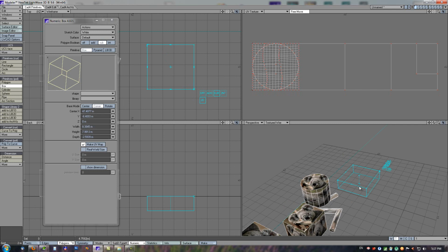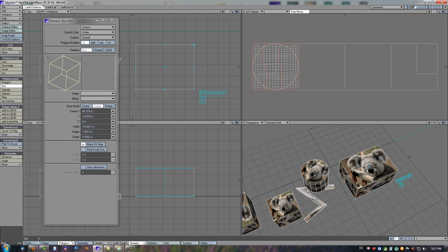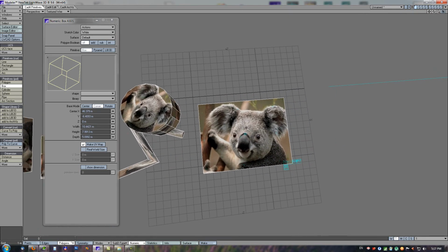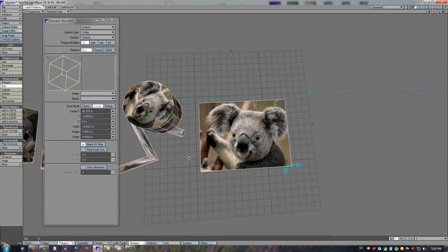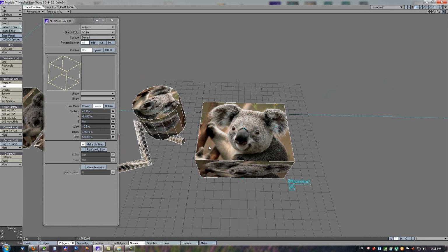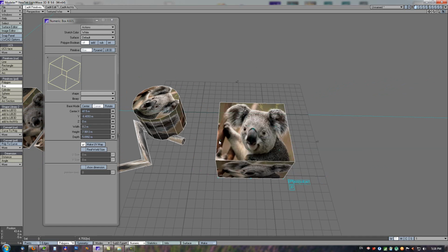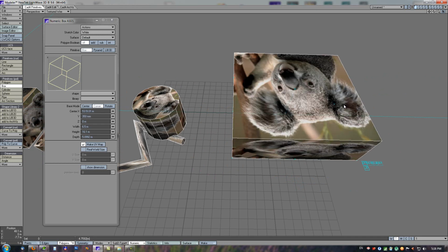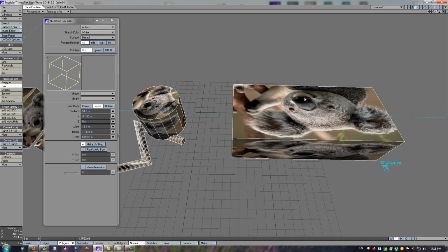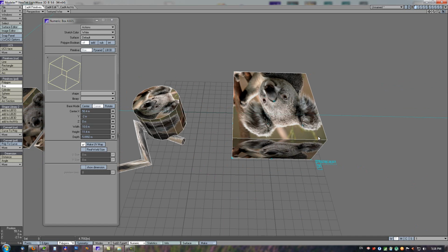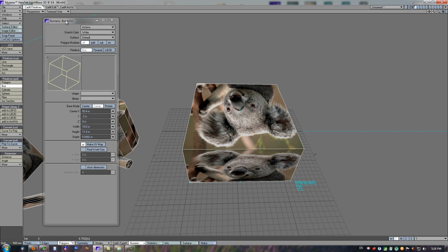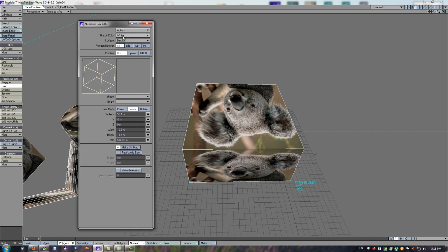Some good, nice features: let's say we can flip the UV map on this box. Now it is easy, just drag the handle from left to down and we can flip UV mapping. No need to change any options. And there is also one more additional new feature, and it is here in the numeric panel.